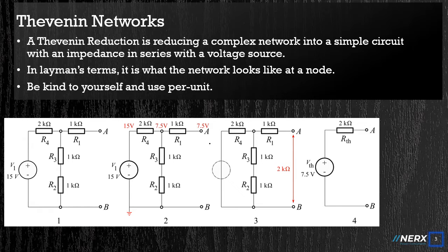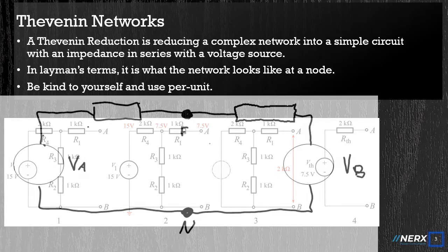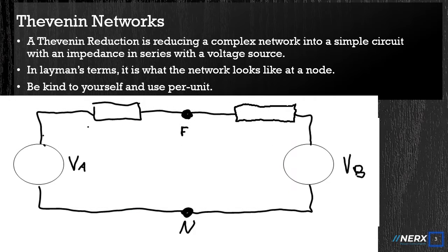When doing studies, a utility will often provide the Thevenin impedances or instead the available 3- and single-phase fault currents. The networks allow the analysis to be focused on the area of interest. The reduction might be just to a single voltage source with a series impedance or to two networks, like for a fault on a line where both ends of the line are of interest.